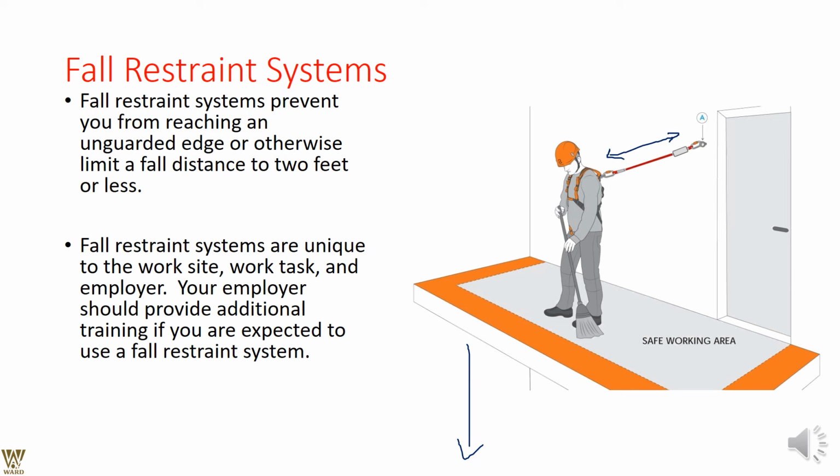This might be a tall building altogether. He might be standing or cleaning on the 22nd floor, probably on the 50th floor. Any floor, remember, beyond the fifth or sixth, is very dangerous. In fact, even up to the fourth floor, people might go to eventual death if they fall. So it is better to have a safe working environment, have the fastening system. You should always have the fall restraint system in place, fall arrest system in place if you expect any untoward